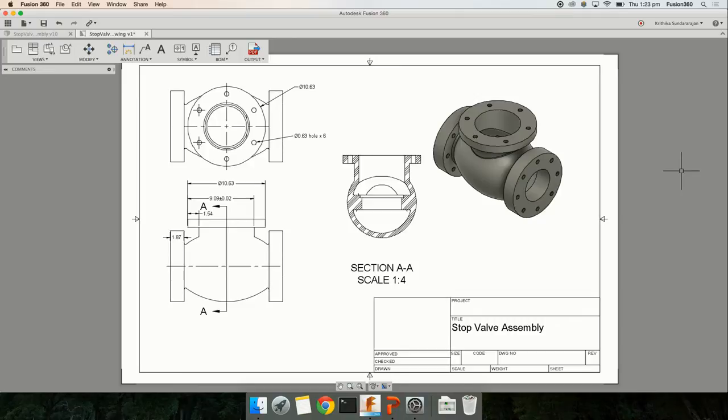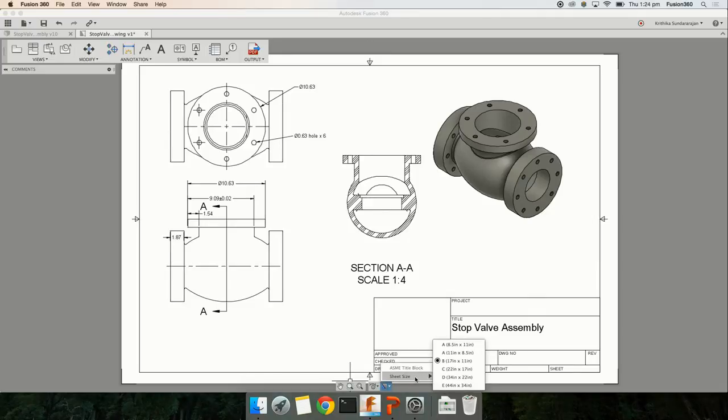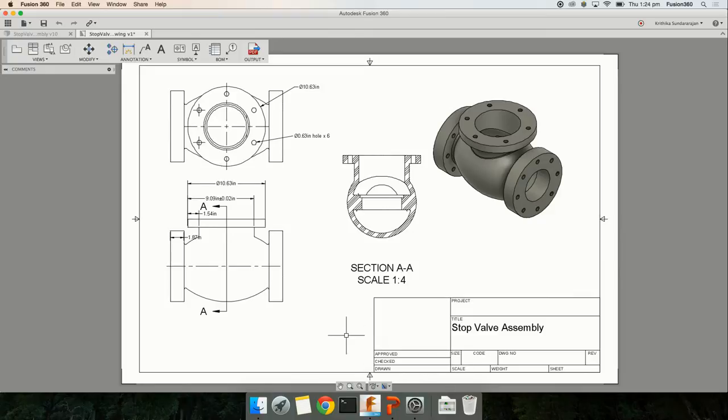Yeah, that's right. Okay, so one more thing. Here we have the different annotations, but the one thing that I'd like to see which is not there is what units they are drawn in. And you can do what we did earlier to go ahead and edit them individually, but instead if you want something that controls all of them, at the bottom here next to the navigation bar, we have some options for the drawing settings. So like here there's sheet settings, which will let you change the sheet size, and next to that there's annotation settings, which will help you change things like the font, text height, precisions, annotation units, and trailing zeros. So in this case I'm going to choose annotation unit on. And that updates all of the existing annotations and newly added ones as well.